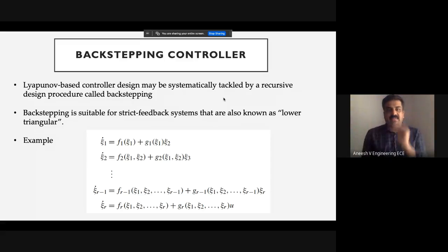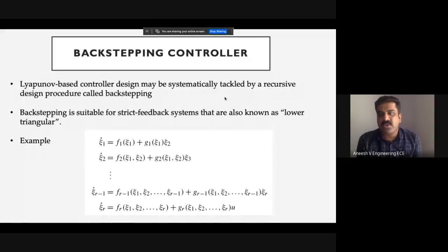Based on this, we have a Lyapunov-based controller structure. A Lyapunov function means a radially unbounded function having a positive semi-definite variable. Positive semi-definite means if we have a function V of x, for x equal to 0, then V of 0 is equal to 0, and V of x should be greater than 0 for all other x. So this thing you already know in the control theories.